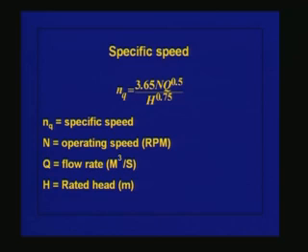In the pump selection, one single most significant factor, or significant parameter or number, whatever you call it, is the specific speed. Just like for flows in pipes, Reynolds number is the most significant parameter, or in open channels Froude number is the significant number. Whenever we talk about pumps and pumping operations or pumping selection, specific speed is a significant number that we have to consider.